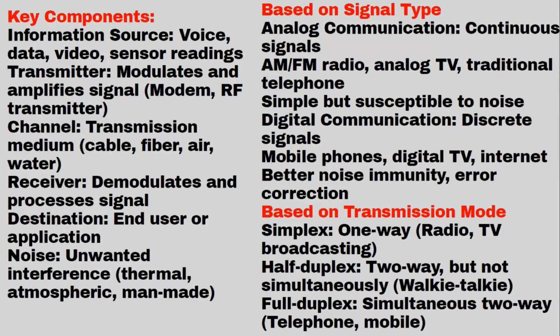Okay, now we will discuss the key components, that is information sources. Voice, data, video, sensor readings, these are information sources. I told you two slides before that you have to remember the diagram, the information source. Then the transmitter, what is a transmitter? It modulates and amplifies the signal. That is modem, RF transmitters. These are the transmitters which will have some power to send the signal outside, right?